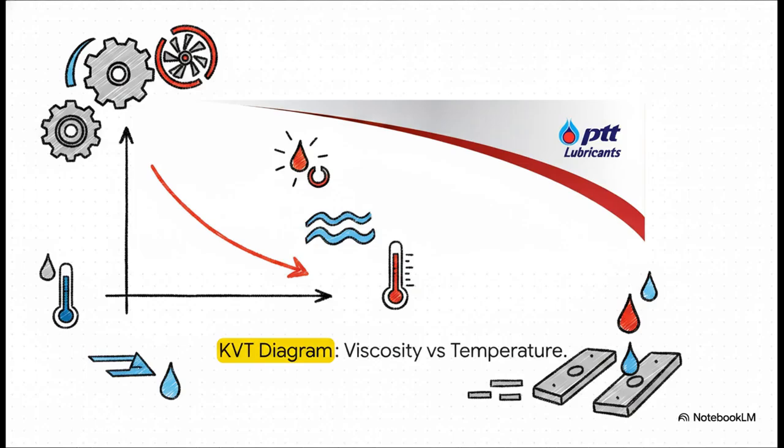When we map out this oil's kinematic viscosity against temperature, we can see exactly why it works so well. The data clearly shows how the oil's viscosity, meaning its thickness and flow rate, behaves across massive temperature swings. And maintaining a solid viscosity index is absolutely make or break here. Whether the turbine is just starting up at 40 degrees or running blazing hot well past 100 degrees Celsius, the oil has to maintain a stable enough viscosity to keep those moving metal parts separated. That specific thermal resistance is what extends oil drain periods and protects the super delicate high-speed bearings that hold up the entire rotor assembly.